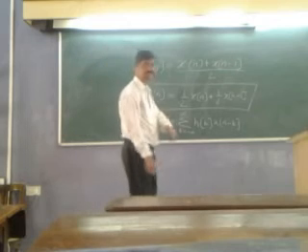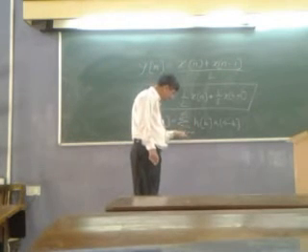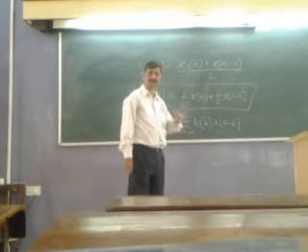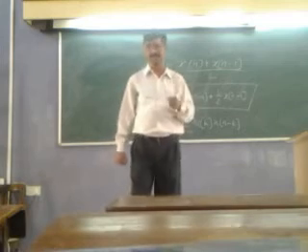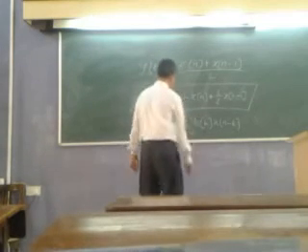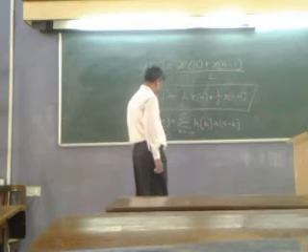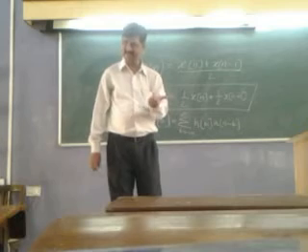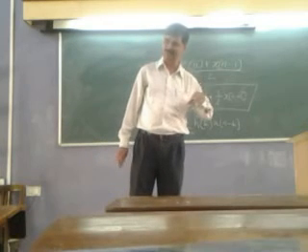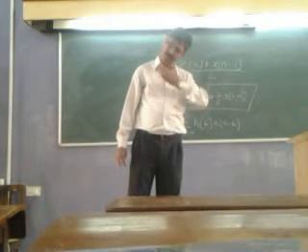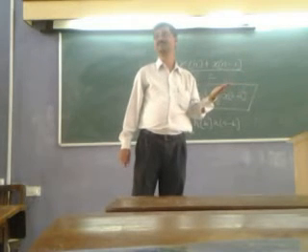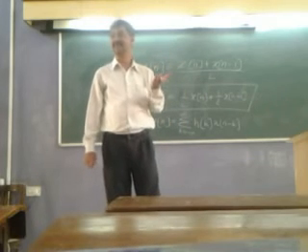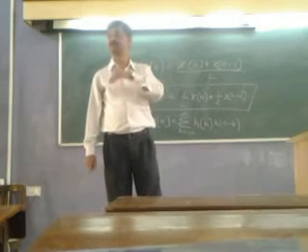Now for a causal system, hk for k less than 0 must be 0, because otherwise I can write Yn is equal to h0 xn plus h1 xn minus 1 plus h2 xn minus 2 and so on, and similarly h minus 1 xn plus 1, h minus 2 xn plus 2.